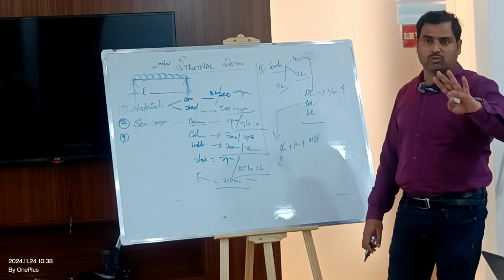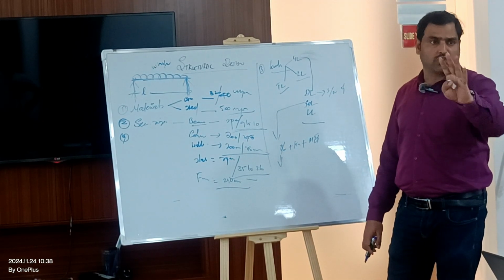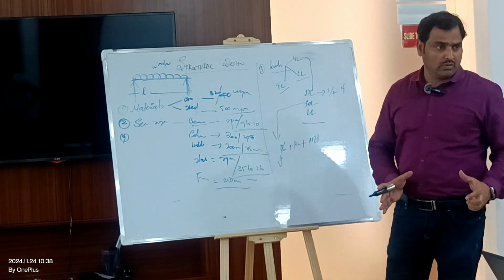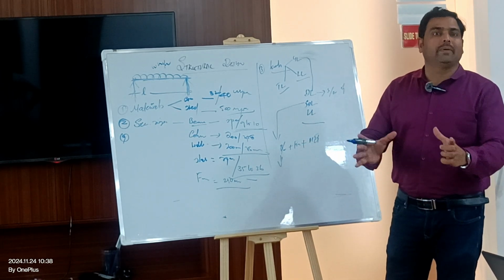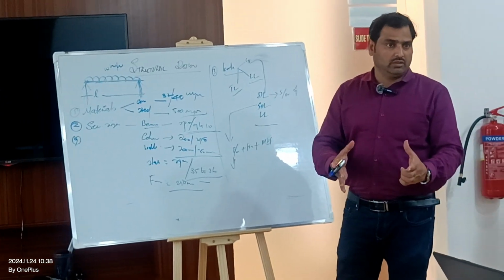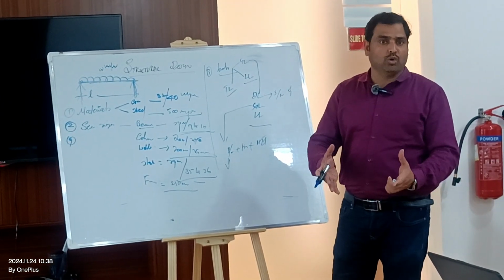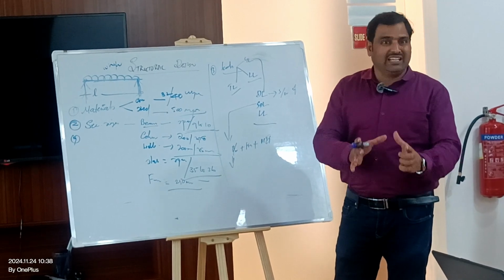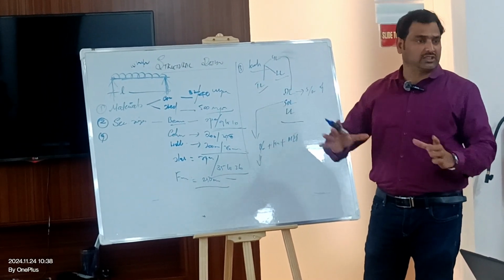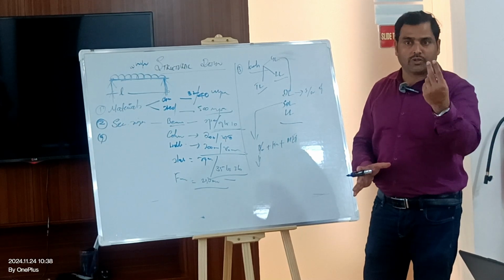Maybe anything which is required by MEP, where the fire rating is higher, because solid block work will take more than 2 hours fire rating. For the entire structure, this is only peanuts, maybe not even 2%, 1%.